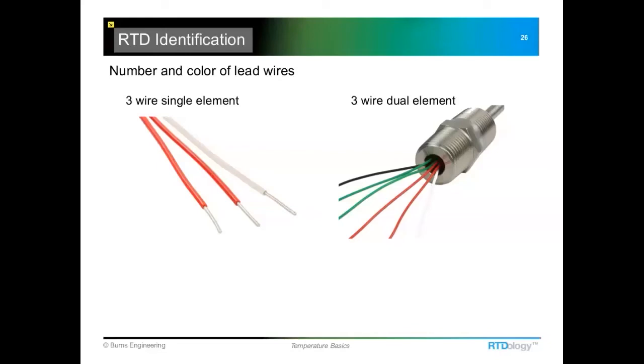Once you actually get into process industry, if you're actually making a product, cleaning a product, sterilizing a product, those types of things, it tends to be much more RTD or thermocouple based. That's kind of the way that the technology has developed over time.